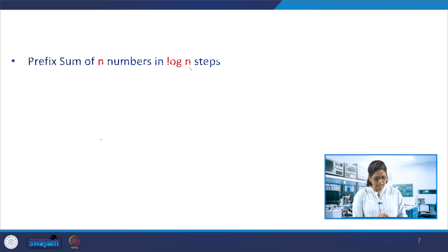So from this technique, the prefix sum is computed using the recursive doubling technique, where for n numbers it takes log n steps. So 3 steps, at least, and then at the 4th step you get the output. If we use this prefix sum computation for prefix carry, shall we use this recursive doubling technique in that? If we use prefix sum alone, it takes n steps. Here the number of steps in the recursive doubling technique gets reduced, so the high speed carry operation can be done, so the carry can be obtained in a few steps.